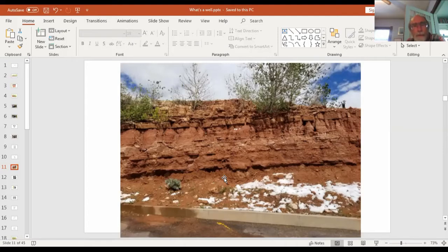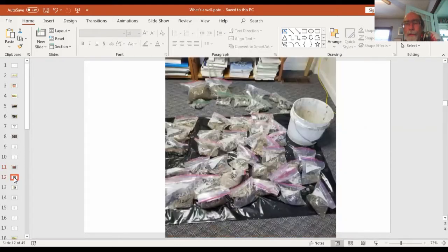And then all that's coming back to the surface, either with compressed air or with a thin mud or just water. And in the end of that process, you've got samples that you've taken as you drilled along. So here I am at 100 feet, and I grab a little bag of stuff, and I go down to 105 feet and grab a bag of stuff. What you see here laid out on my office floor is a well that we're working on up at Jackson, and each one of these little baggies is full of dirt that came from a different depth, circulated back to the surface with a thin mud system in this case.